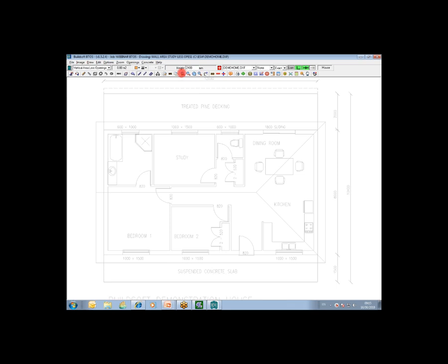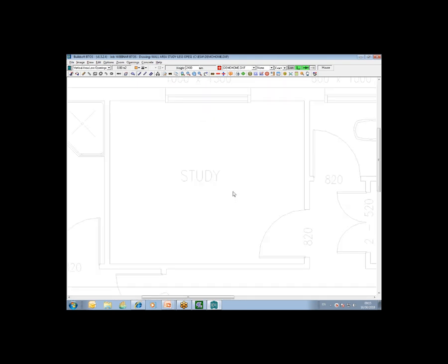As before, task number 1 would be to zoom in on the section of the drawing that you want to work on. So I'll click on the zoom on a section of a plan. Just click on it once, move away, click and hold, drag, and let go. And as with any area type takeoff, you pick a point that you want to start on, click, with the next point, click, with the next point, and so forth. When you get to the last point, bear in mind that you cannot manually join, so you have to press J to join the first point to the last point.